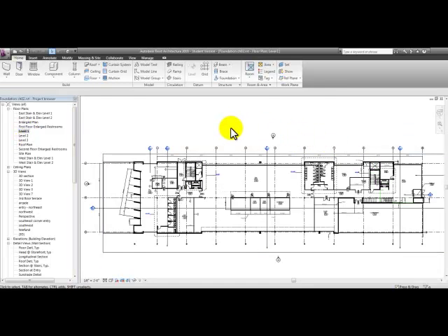Revit uses a different language than AutoCAD for basically the same items or concepts, like using the word elements instead of objects and the word tools instead of commands, and sometimes you will hear both. Many tools are similar but have taken on new names, like the split tool compared to the break command, and the array tool with linear and radial compared to rectangular and polar arrays. Let's take a look at the Revit interface.